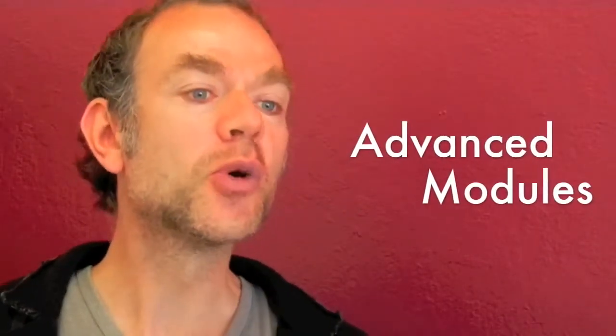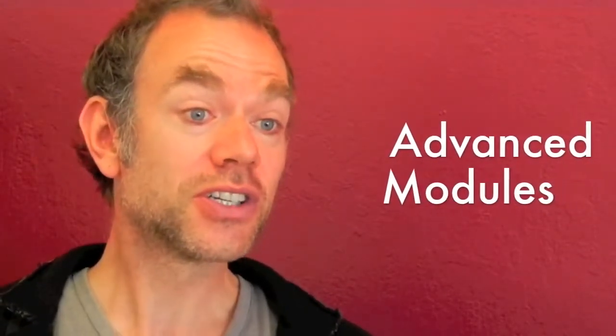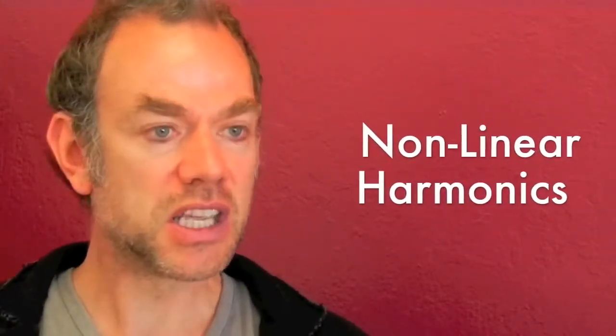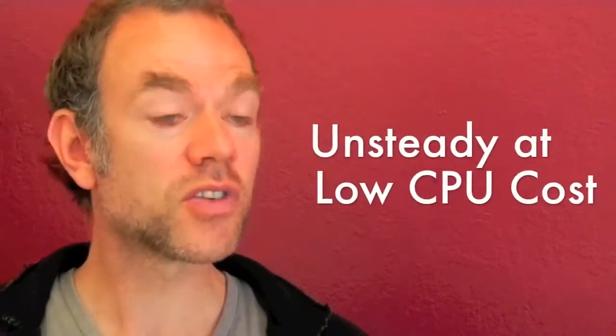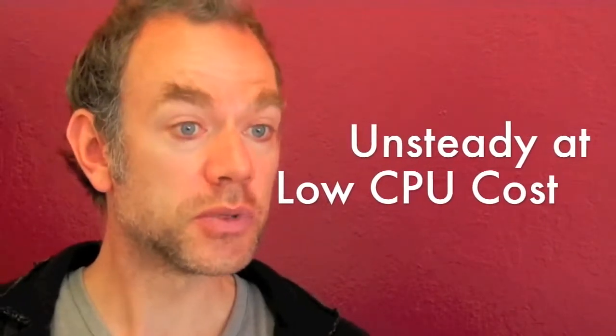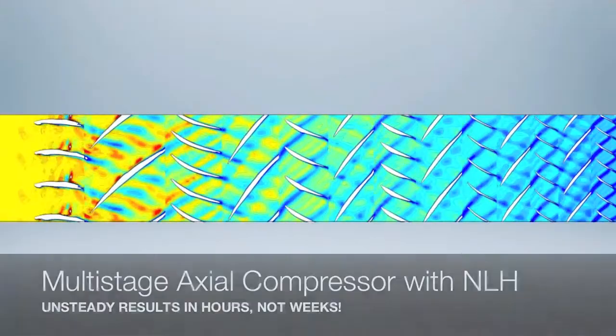An important module of the Fine Turbo solver, which generated a lot of interest over the last 5 years, is the nonlinear harmonics. So this is a technique that allows calculating unsteady flows in turbomachinery and rotor-stator interactions at totally affordable CPU cost. NUMECA integrated the pioneering nonlinear harmonic method into Fine Turbo.